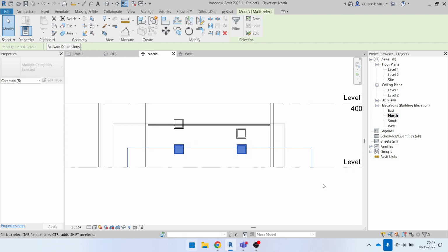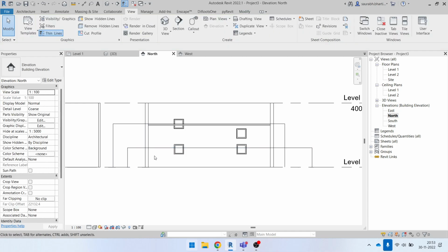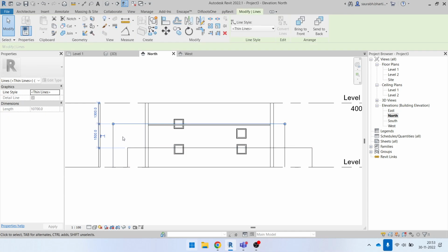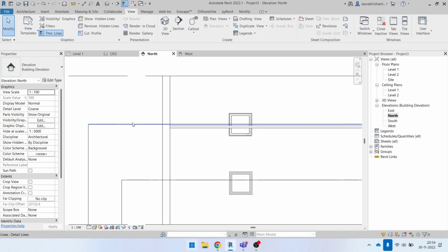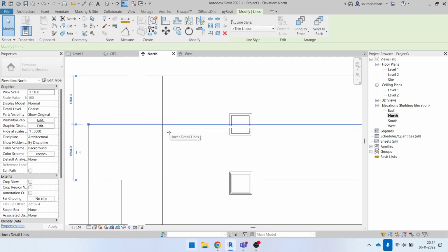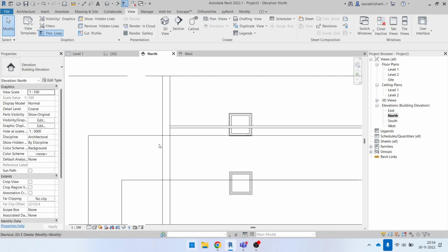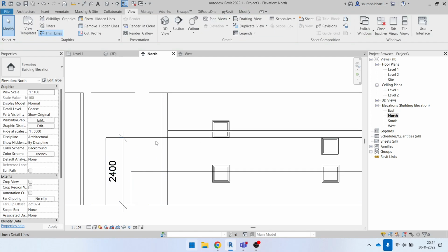new plan. Okay, so this is the area that you are seeing. This is the cut plane area when you are making a floor plan, and we have to change it to this one. When you have to see the ceiling, you can keep the view range over the top of this plane. Okay, so if I reduce it, if it is right now 2500 mm, just for reference, this is 2400 mm.